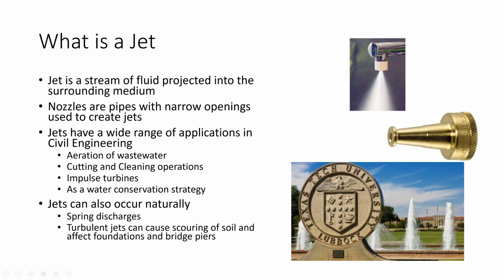As the diameter goes down, you know that the velocity goes up. So the fluid leaving the nozzle has very high velocity, and that high velocity, through inertia, causes the water to move further along against the force of gravity for a certain distance before gravity takes over and it starts to fall back.